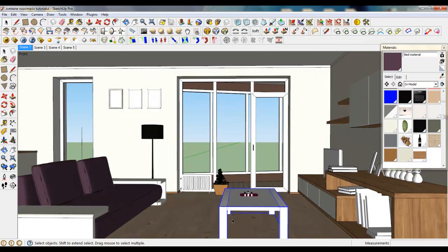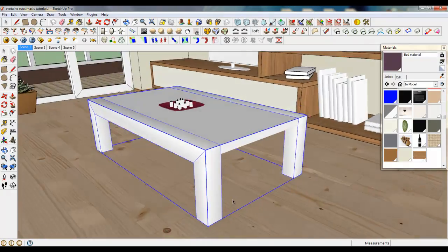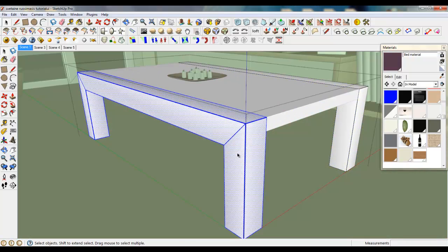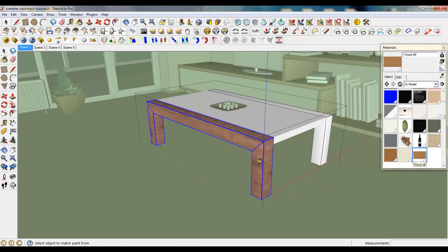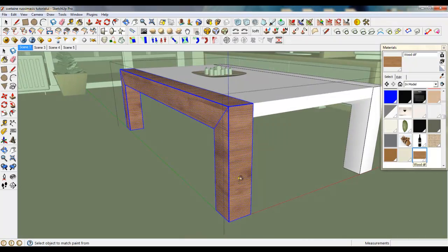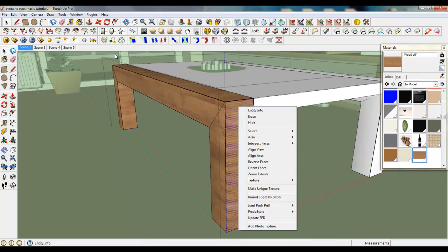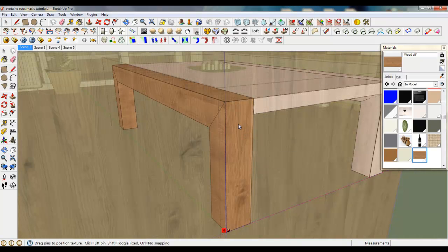Let's now texture our table, and the table is simple to texture because we have prepared for it. So open, and we have this flag. So select everything as I said, map, and now you see on the vertical planes we have horizontal texture, so we need to rotate it to make a better position. Turn on hidden geometry, texture, position, and rotate it by 19 degrees.